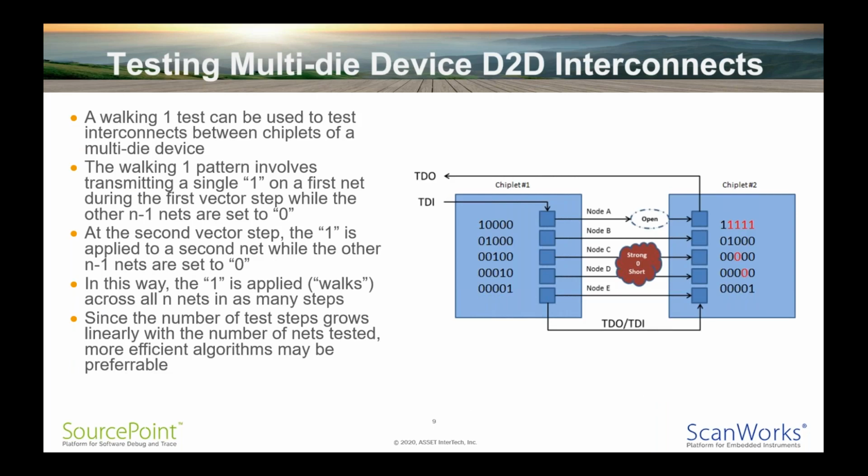When testing die-to-die interconnects, possible shorts, opens, stuck-ats, and bridging faults must be considered. Since the boundary scan path in each multi-die device provides direct access to these nets, test patterns can be generated which provide coverage for these faults. There are several preferable patterns which detect possible faults.